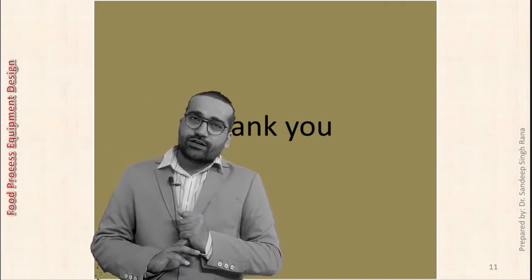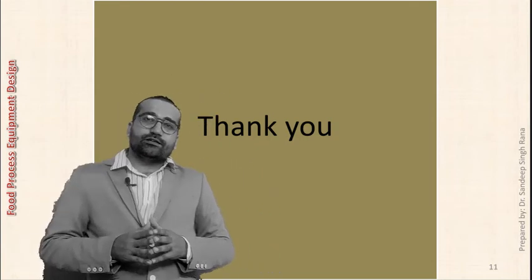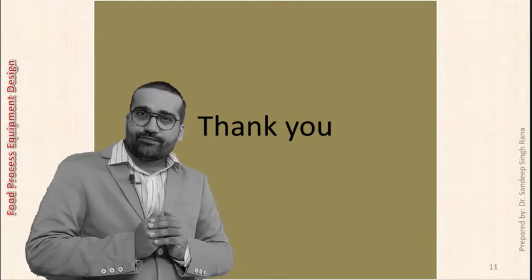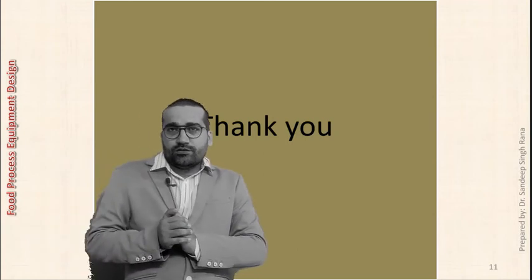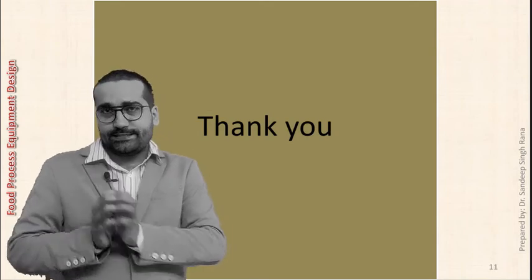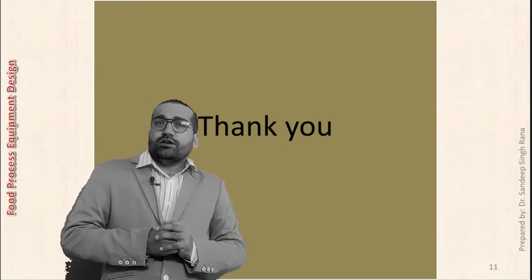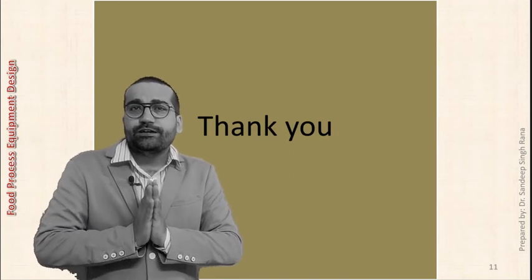There is also one consideration for fouling. Whatever the heat transfer or whatever the size we are getting for the tubes, we multiply it by a factor of 1.25. That is for fouling. Generally the fouling factor ranges from 1.25 to 1.6 depending upon the properties of the material we are using. That is the consideration for fouling factor. So if we consider all those things, we are able to design the shell and tube type heat exchanger.